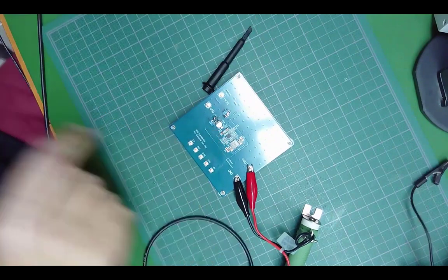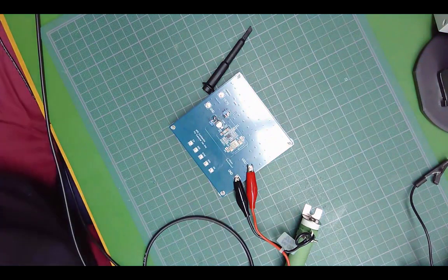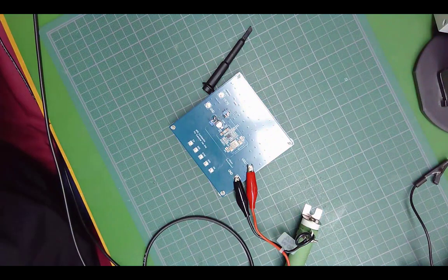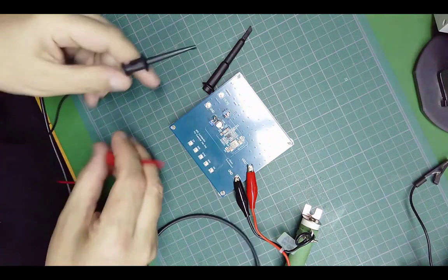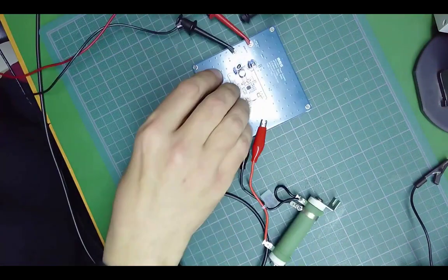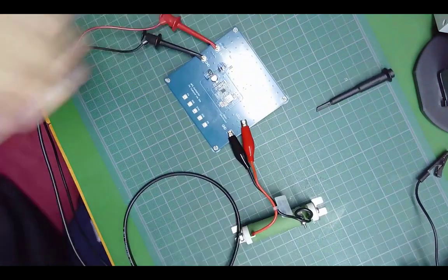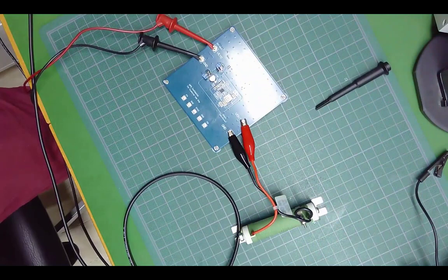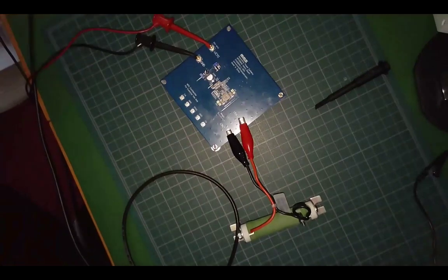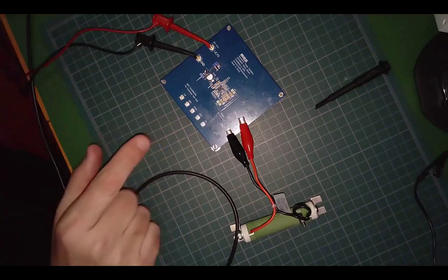So let me power the board and see how the emissions are, okay? For the people that were not attending the first webinar, this is a DC-DC converter. It's a buck converter that steps down the voltage. I am going to power it with 20 volts, and I have here a resistive load to make the circuit switch at maximum load. Let me switch off the lights and switch on the lights in the camera, so perhaps it's better, okay? And now, let me show you the emissions when I switch on the device.